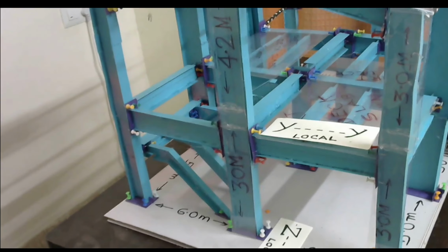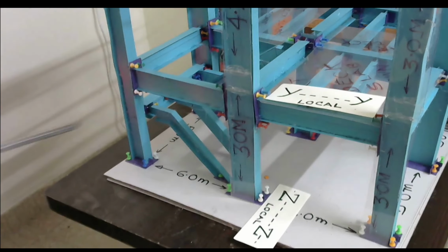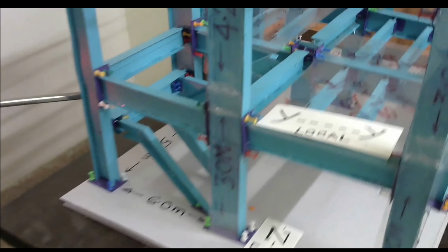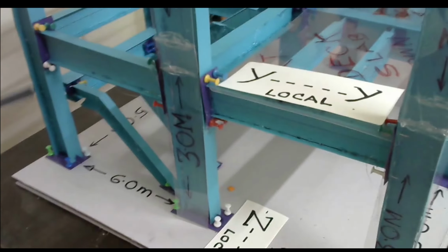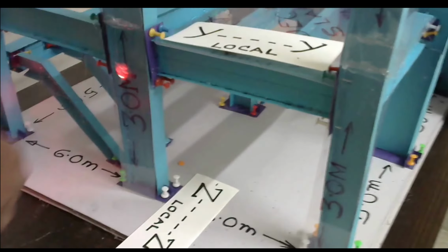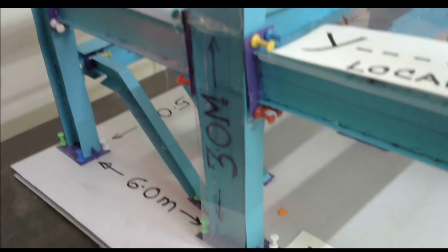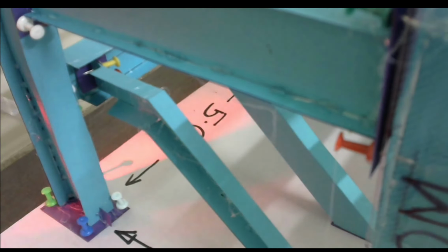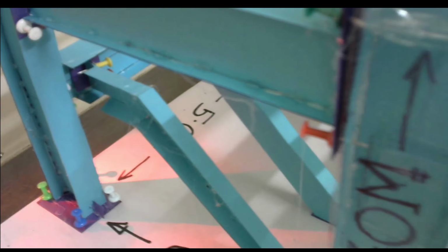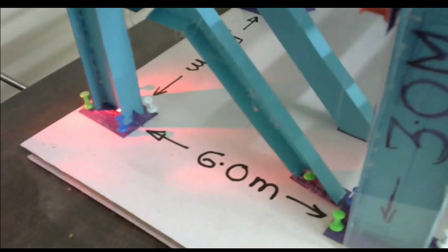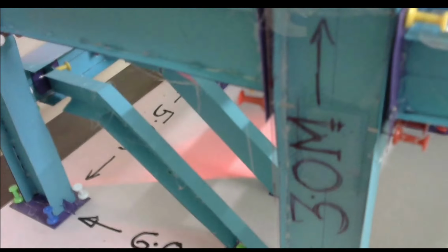For this column, there is a restraint. There is a mid landing beam here. You can see this mid landing beam, at the middle of the strip. But the connections are pin connections. A cleat connection is here. You can see this cleat connection, a simple connection. So it is hinged at bottom about the LY direction, hinged at top in the LY direction.